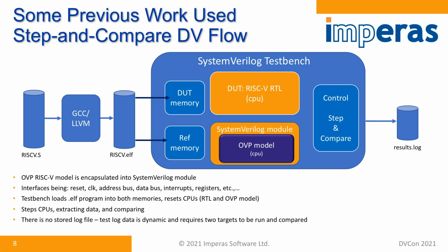It's for the device under test to actually be able to tell when an interrupt has happened, be able to tell the reference model exactly what's happened, how the interrupt is being handled. And then when they get to the end of the instruction retirement, then the comparison is done. So the comparison is done dynamically as well as being able to step and compare.